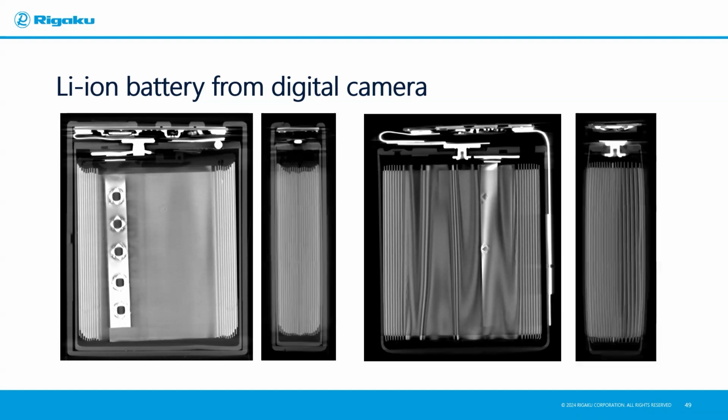And if we look at a 2D cross section 90 degrees relative to that, then you can see why that happens. The good battery has very uniform thickness for the layers, but for the bad battery, you see some expansion and the layers are no longer uniformly spaced. So that's why you're starting to pick them up when we take the slice through the middle.